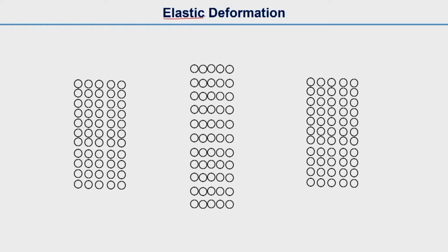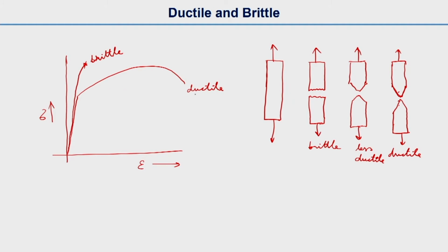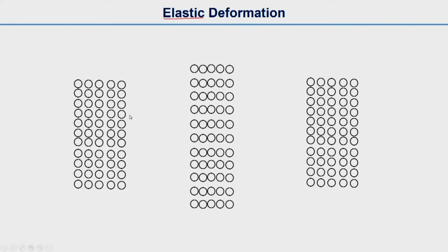As you know, in the stress strain curve, in the earlier stress strain curve, let's say for this ductile material, the elastic part of the stress strain curve is this one, that is the straight line, mostly elastic. In these lectures we will focus only on metals, not on ceramics and polymers. That's why we are talking about crystalline metallic materials, and we will focus on that type of stress strain curve. So this is a material, let's say your tensile specimen.